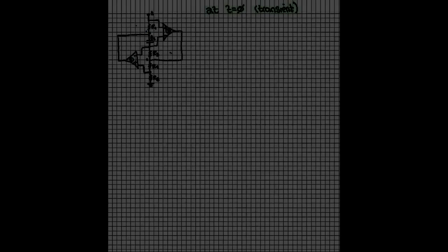So let's write that. I feel like sometimes it's easier for people to understand. We'll raise its voltage at VO2, that's that node right there, to make VN2 equal to VP2 equal to VA. Remember, to make the two inverting and non-inverting terminals equal.